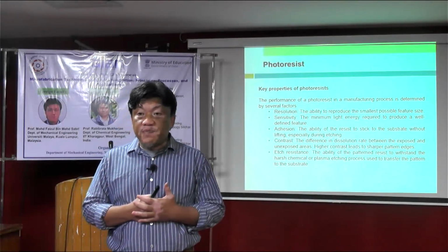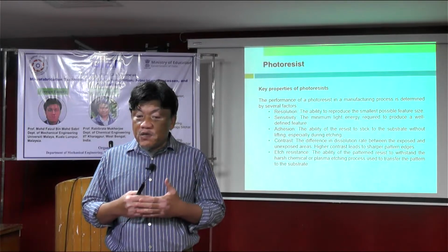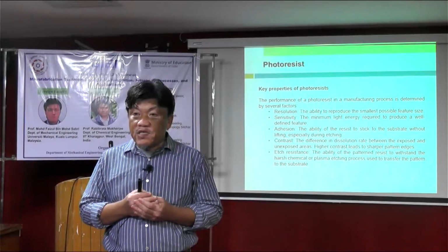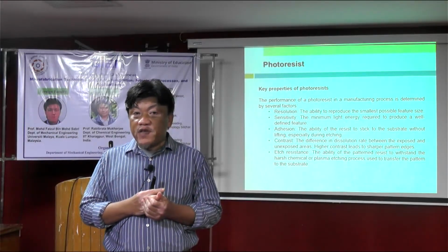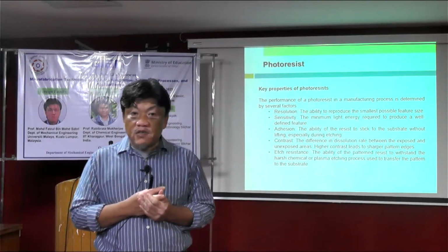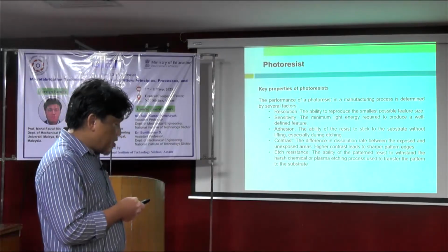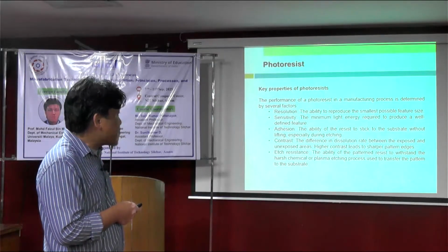The longer you expose, the more your pattern won't be as intended, meaning it might go beyond the size that you have designed, because with longer exposure light scattering might happen. So you want to have high sensitivity to a certain extent.